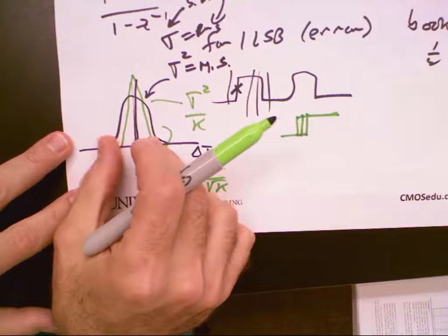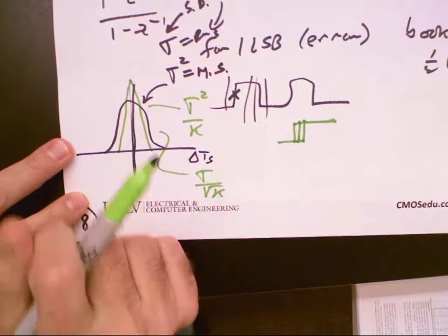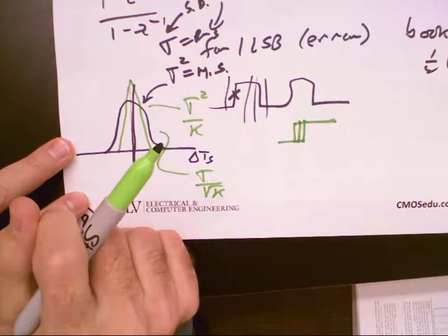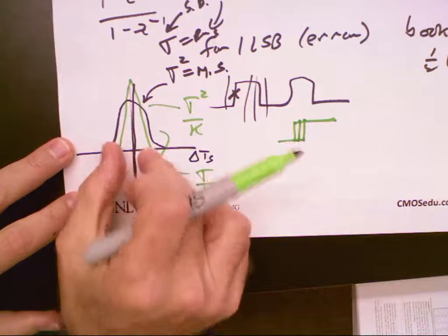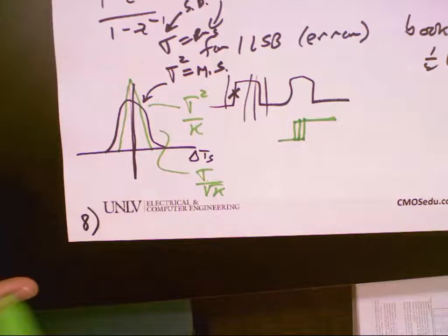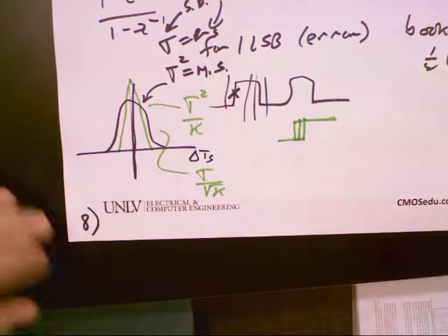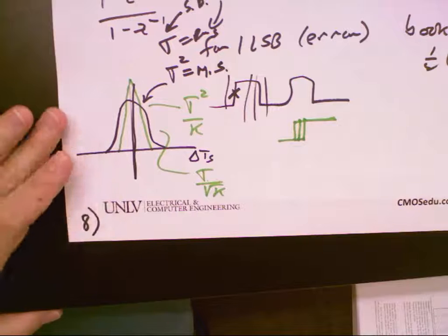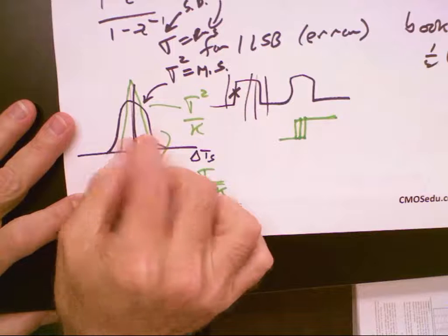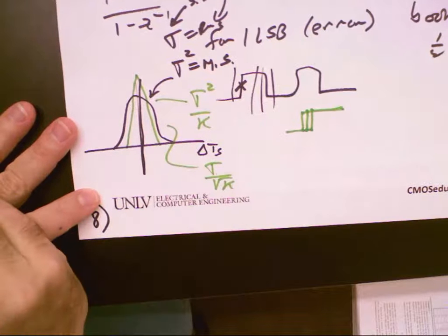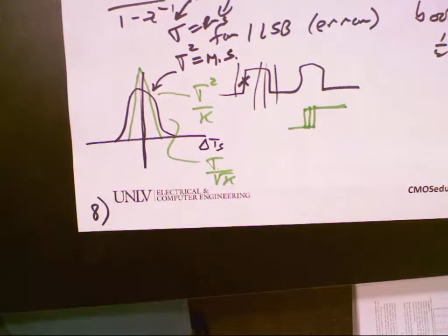And we're going to use this to get around a lot of these problems we're talking about, averaging points so that we get less variation. So I'm just planting that seed in your brain. If I use an average of clock signals over and over again, sometimes early, sometimes late, it tightens up the distribution by the number of points that I average. So if I use a really big K, like 1,000, I get a really tight distribution, and then my jitter becomes much less of a concern.